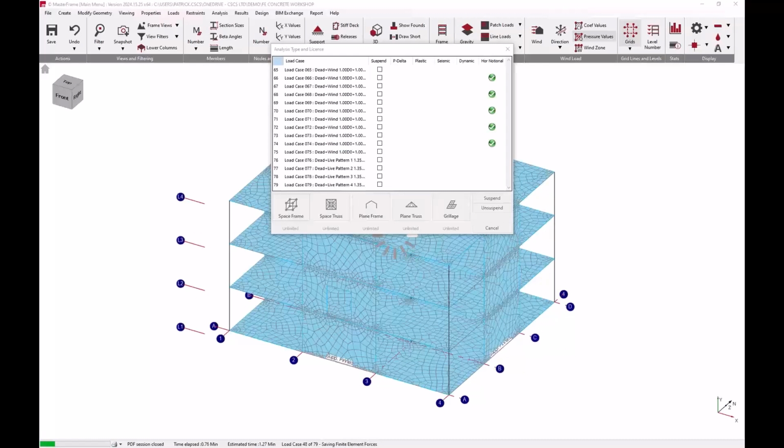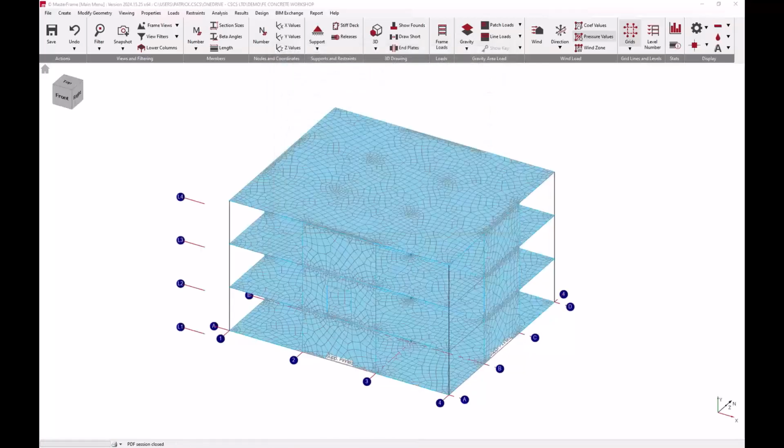Is it possible to form steps and openings in slabs? Yes, you can define openings in the surface, which we defined earlier. And to create a step, you just need to split the FE surface up into two separate surfaces and then assign your different thicknesses accordingly, and then whatever connecting elements you have there. Can we get a copy of the load case template file? Yes, I'm happy enough to save that up and post it with the rest of the model files and details.